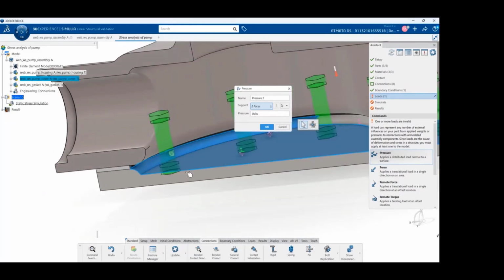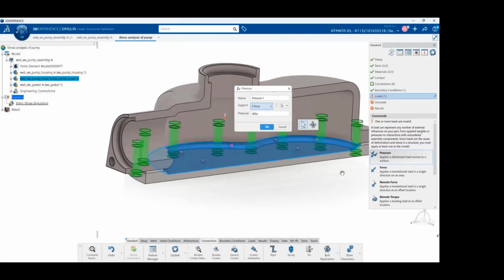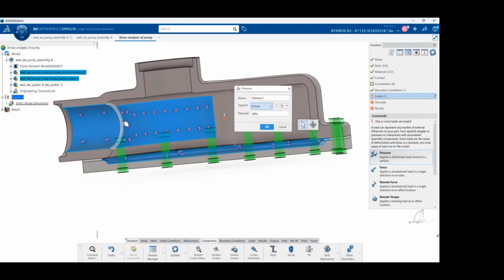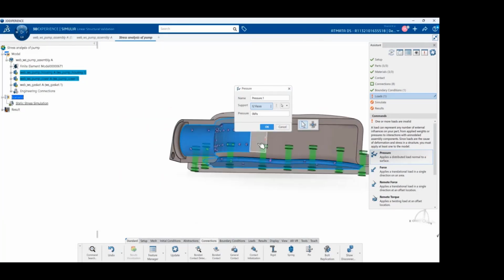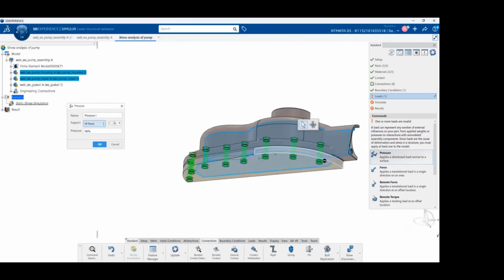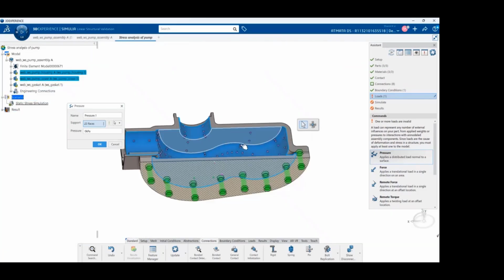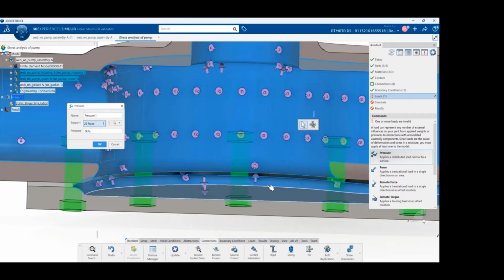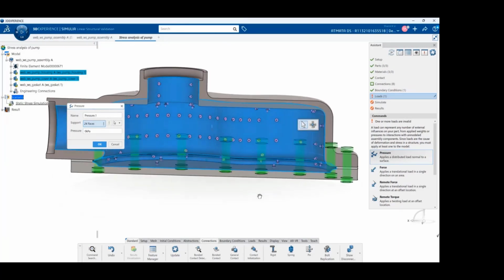Make sure I define it properly on both locations, and all the rest of the locations where you have a boundary condition. So as engineers, you have to take a call on how exactly your loading conditions are, right? Because whatever loading condition you give, the results will be based on that. Whatever analysis you run, the real-world loading condition, boundary condition, as well as the material property, you need to be more precise with respect to the simulation.